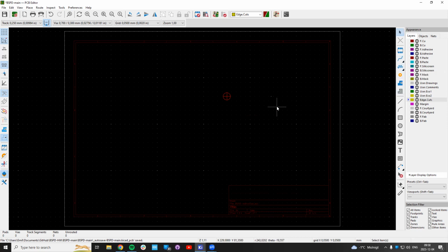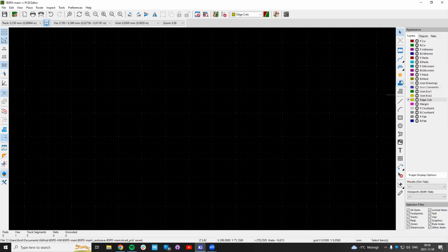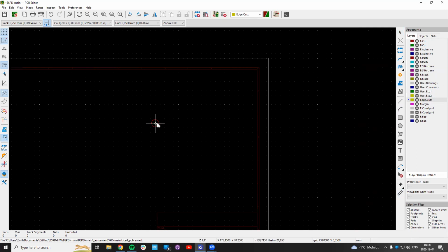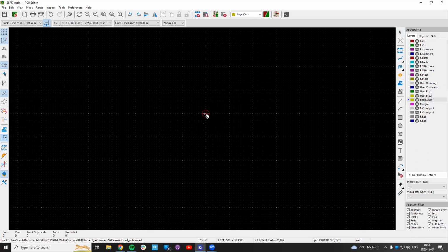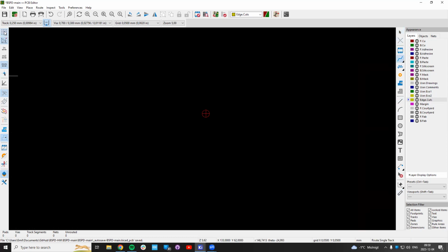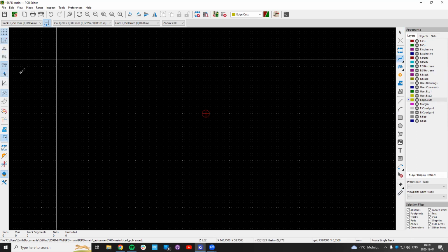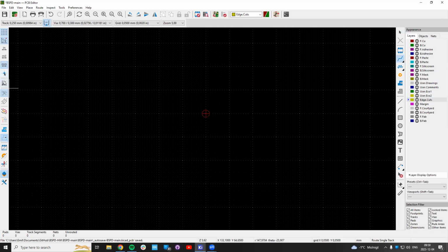To add freestanding vias, you press here. Add filled zone. We'll get to these different drawing tools, measurement tools, another measurement tool, and a deletion tool. Let's see if that works here. Nothing can delete this. Interesting. And then on the side you have options like the grid, what coordinate system you want, distances, and if you want the full crosshair, if you're aligning things. We'll get back to this later.